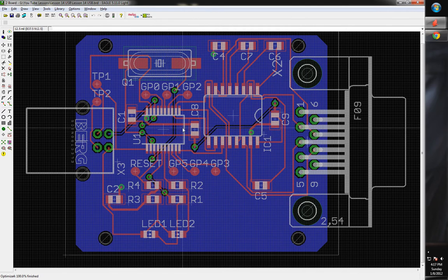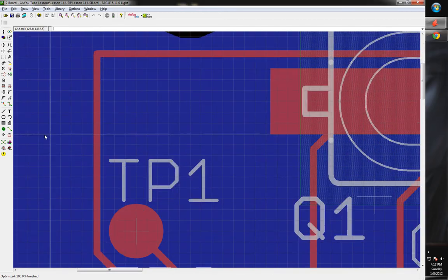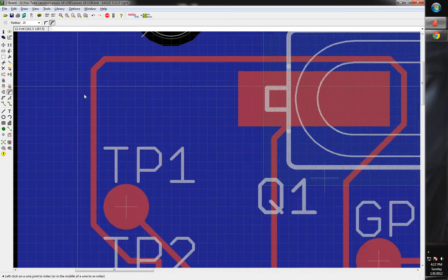So you have to use your miter tool, and we'll do, I don't know, a 15 mil miter. And see, you gotta catch that. So you gotta inspect. So here's another one. You gotta inspect your stuff, because it doesn't care about board manufacturability, and it will put the deals. And see, like this right here, I don't like this at all.